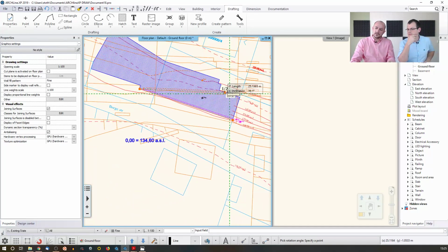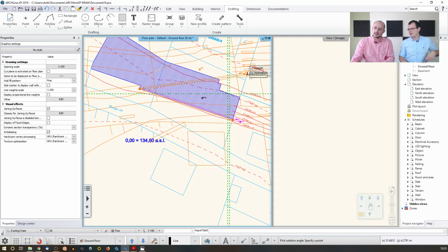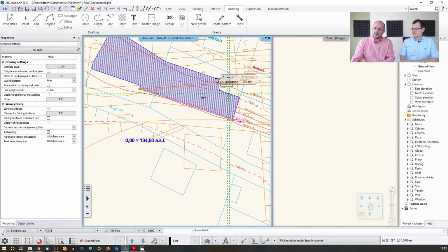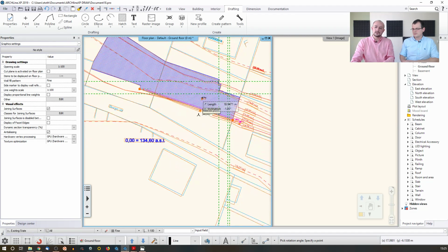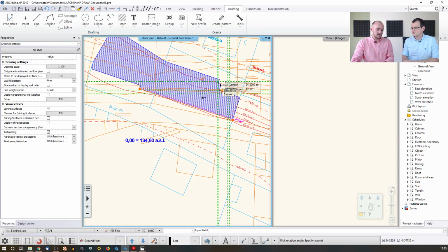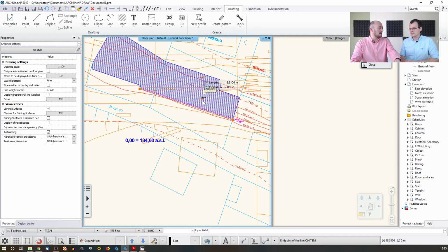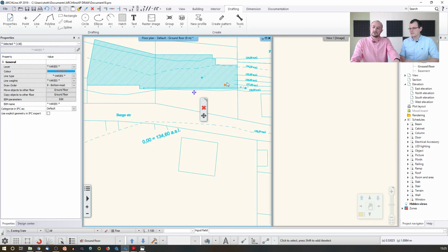And when you have a drawing like this, it's very easy to misclick some places because they're tiny little endpoints and division points and so on. So to be able to lock it to the horizontal direction, just move close to the horizontal direction and keep holding the shift key. This is the horizontal lock, the direction lock. So whenever I move my mouse, see, it's not changing, it's always horizontal. So now when I click to accept it, it was locked and rotated the way I wanted.